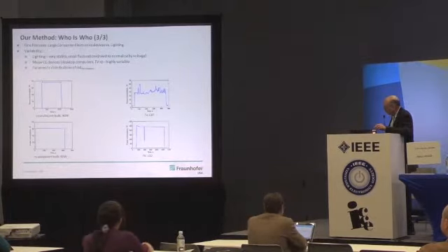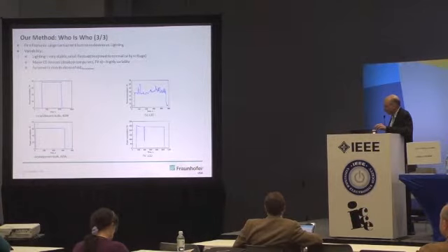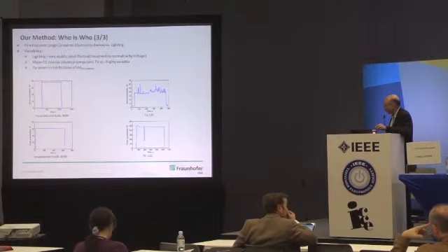For LCD televisions, those variations are usually smaller. However, every time the homeowner changes the channel, you will see a significant drop in power, something like that. Because this end use is usually confused with lighting, we need to be able to distinguish between these two. So let us use a fine feature such as the standard deviation of the signal between times on and off. For consumer electronics, it will be relatively high. For lighting, it will be very low.